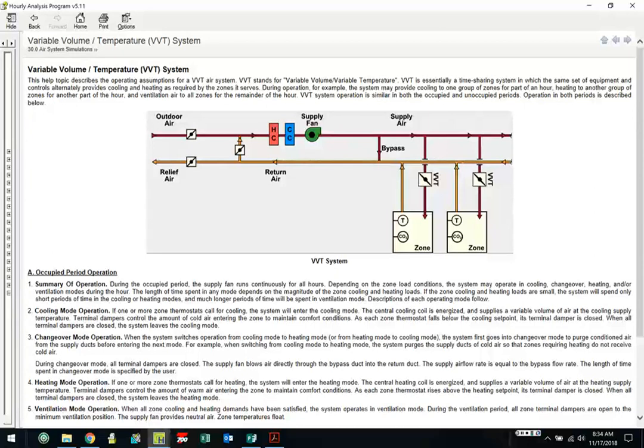What we're really doing is we're making this rooftop unit, we're zoning it out. And some of the problems we can run into with this is if I have a lot of zones that are not calling for heating and some that are heating, and I put the unit in heating mode, if I don't get enough airflow across my heat exchanger here, I will stress the heat exchanger and crack it. And conversely, if I don't get enough airflow across a cooling coil, I would end up freezing the coil up, and then it would have to be defrosted in order to get airflow going across it again.